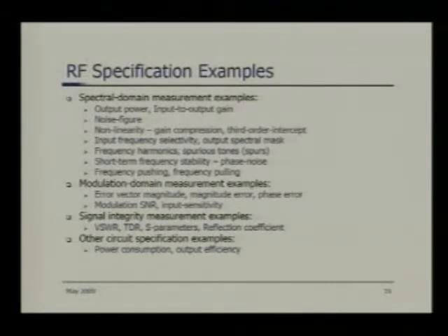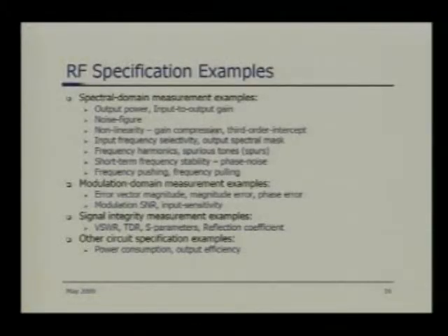It goes quickly into the saturating region, so your gain is going to gradually compress. So you have to characterize it and test for it in production test. Nonlinearity specifications like gain compression and third order intercept will come into the picture. At least for the first few, I am going to go through them in the subsequent slides.